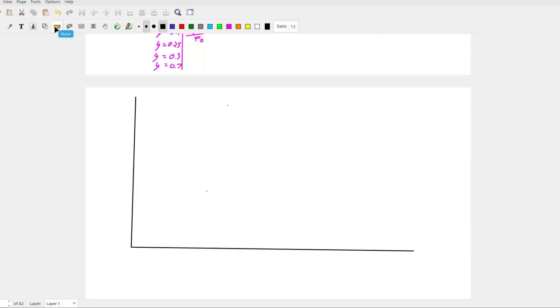All right, so there's my X and Y axis. On my Y axis, this is going to be frequency ratio, and it's going to be centered at 1. Why is it centered at 1? Because 1 is where omega n is equal to omega, which is where our system is going to be in resonance. It's going to be unsolvable, or undefined, if there's no damping in the system.